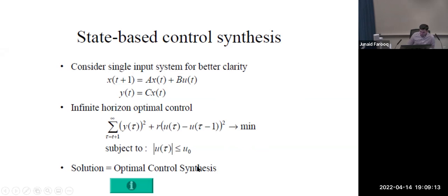But essentially the MPC problem is to find only the next input. So you just need the input for, even though you can compute it for the longer horizon, you will act only on a single step.